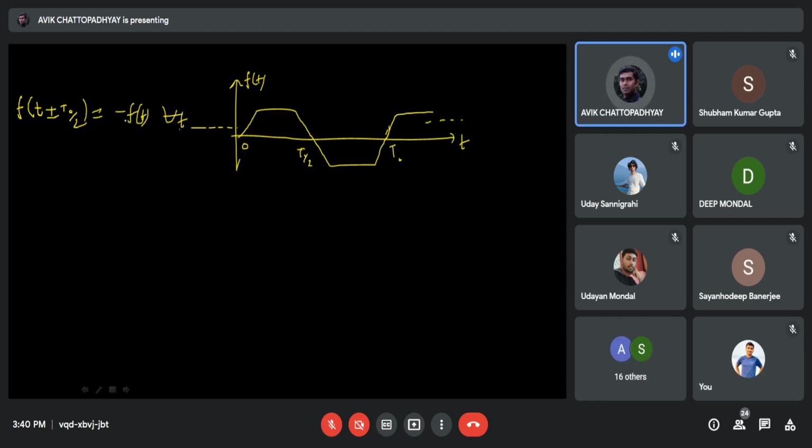So about the horizontal axis. So suppose, for example, if instead of drawing this axis here, you draw the axis here, then it will be like a flipped version of the original signal. So this is called the half-wave symmetry in the odd sense. Now, why is it in the odd sense? Because actually, when you do the mathematics, again, as I mentioned, all this can be proved mathematically. When you do the mathematics, you will understand that here for this kind of